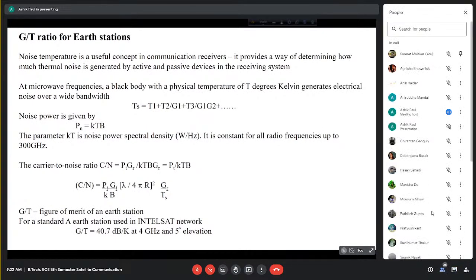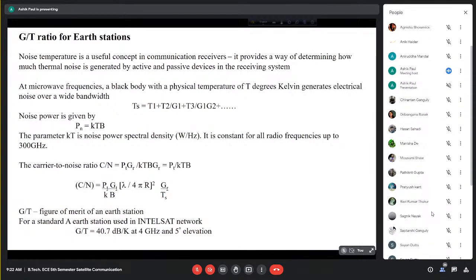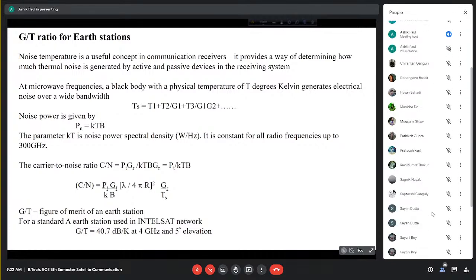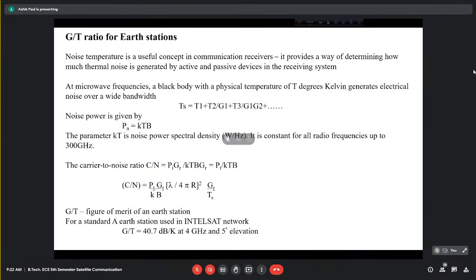That means in all the previous stages, starting from the RF amplifier, then the mixer, local oscillator, and the IF amplifier, basically the output signal was proportional to the input with some proportionality constant. But once the signal passes the square law detector, it is no longer a linear variation of the output with respect to the input. Rather, the output becomes the square of the input voltage amplitude.